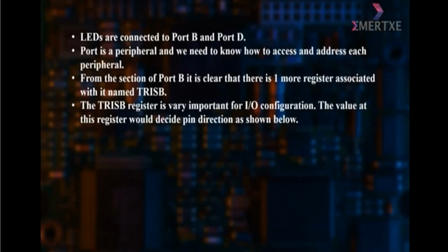LEDs are connected to port B and port D of the PIC 16F877A microcontroller. Port is a peripheral and we need to know how to access and address each peripheral. From the section of port B, it is clear that there is one more register associated with it named TRISB.